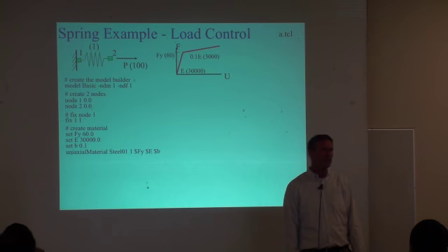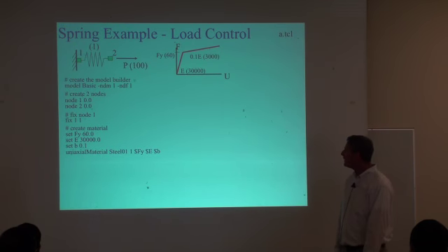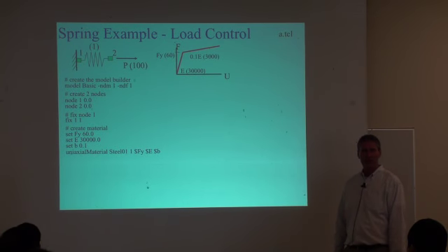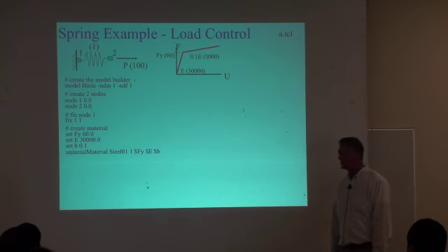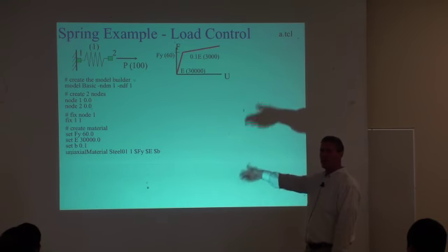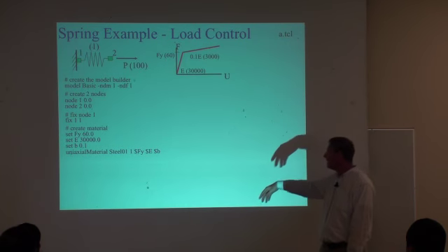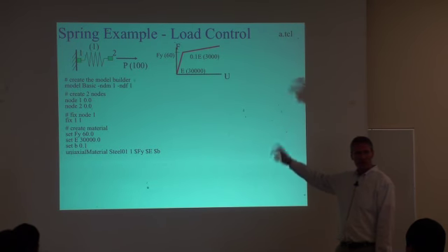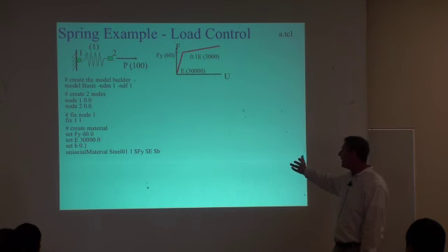Next, I'm going to create my material. I'm going to use some variable definitions here. I'm going to set Fy to be 60, E to be 30,000, and my hardening ratio B to be 0.1. So I'm just using variables. Then when I issue the uniaxial material command, I'm going to use Steel01, which gives me the relationship I want. The tag is going to be 1, and then $Fy, $E, and $B.